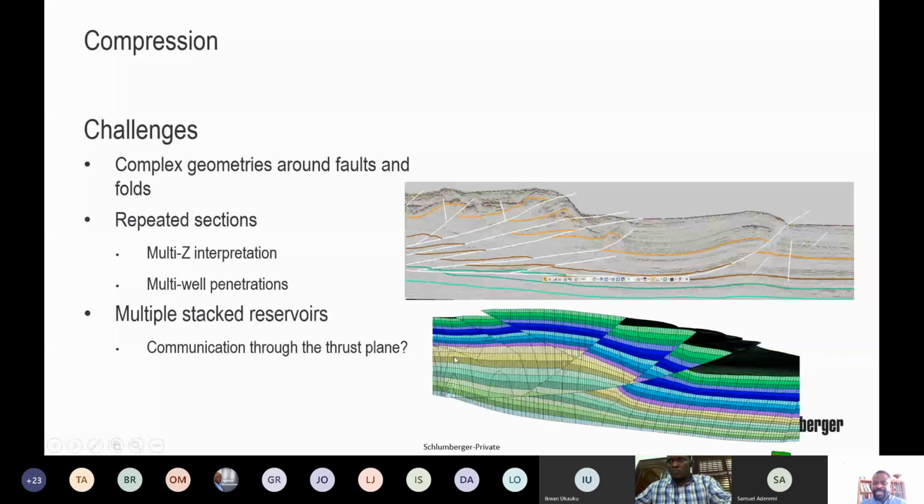One very nice thing, and this is the difference, is we are able to preserve the full fold plane, and the pillars are orthogonal to the surface we are modeling, not to the folds that we are creating. So this allows us to have flexibility to model complex structures the same way we have here.